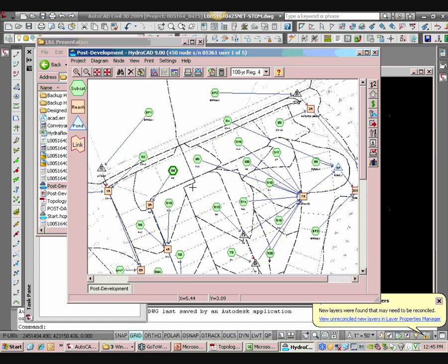Well, I can simply do a quick back-of-the-hand, is this going to work kind of thing. Say, what if I extended this inlet line that came out this way and drained it to this pond? I can just see it, just like that. So there's a big advantage to setting up all your little sub-drainage areas. I noticed I needed even more. So what if I bring this channel? This channel was originally bypassing. So now I need to go back and update my numbers. Okay?